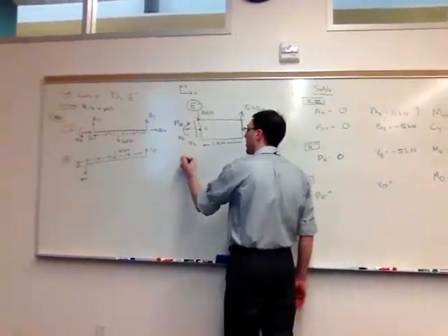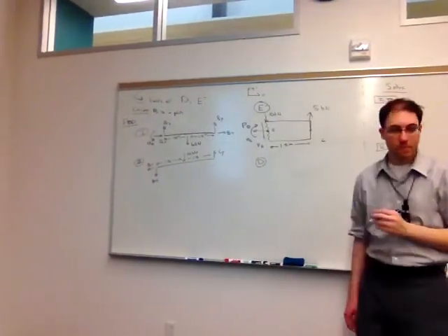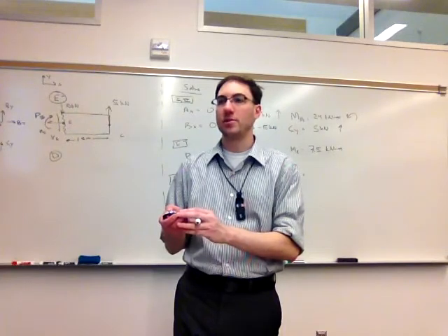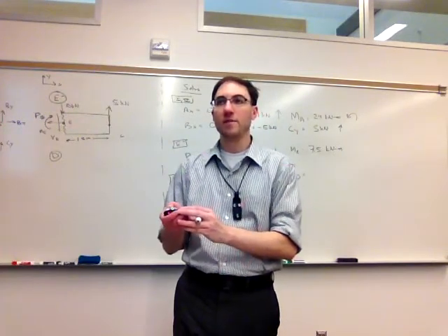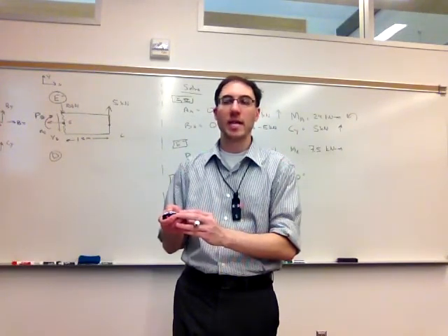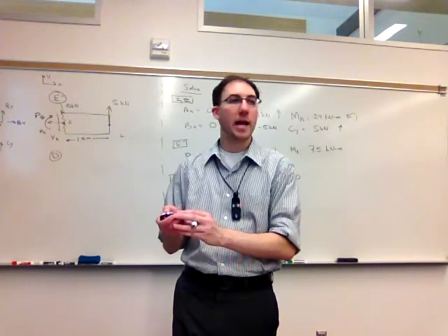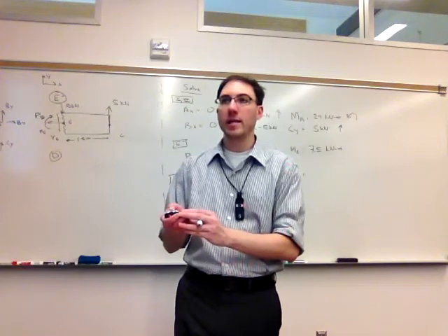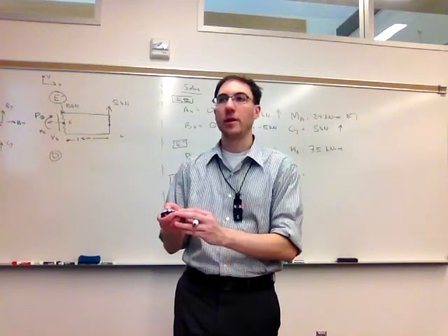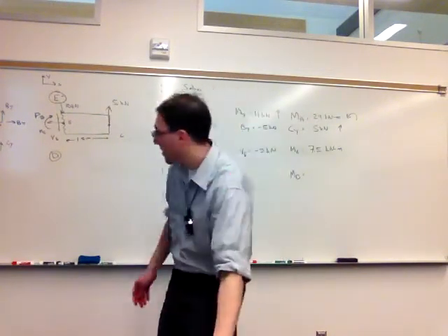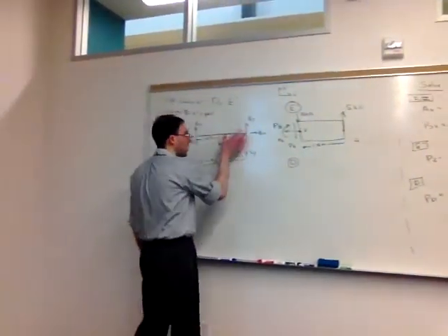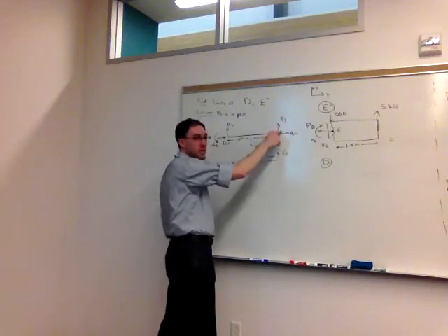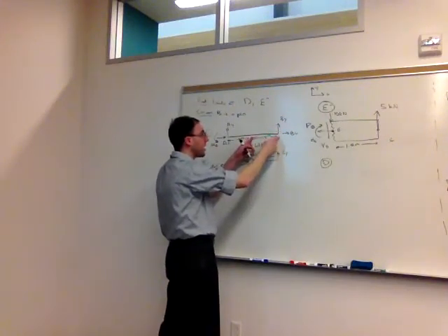Finally, we want to know the internal loads at point D. We have, again, a couple of options. If we make that transverse slice through D, we can take everything to the left, so we'll have a distributed load and what's happening at the wall acting on that segment. We could take the cut and take everything to the right, or everything to the right up to and including B. Again, we include the BX and the BY as modeled in this picture because we're only considering this beam.